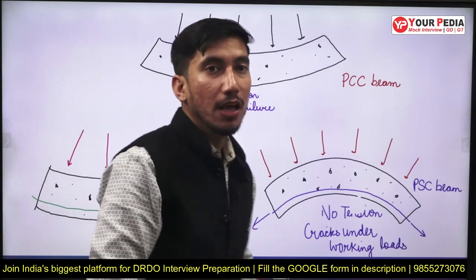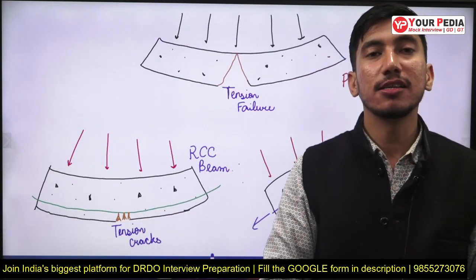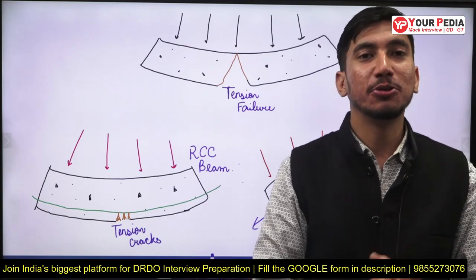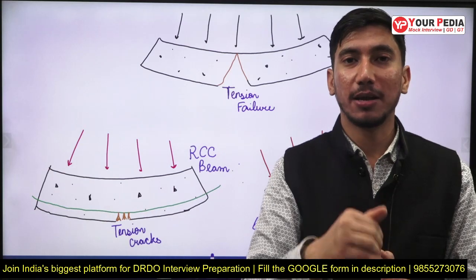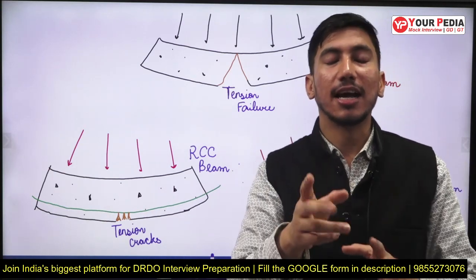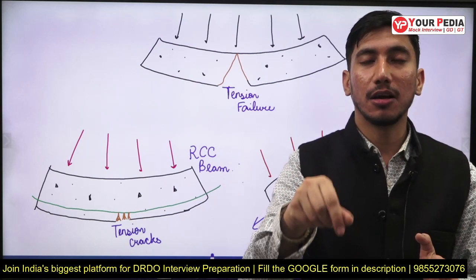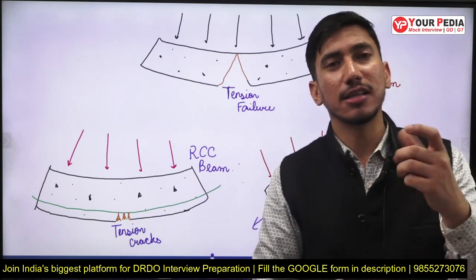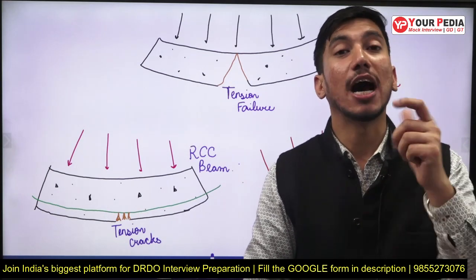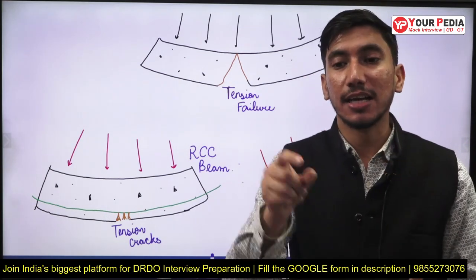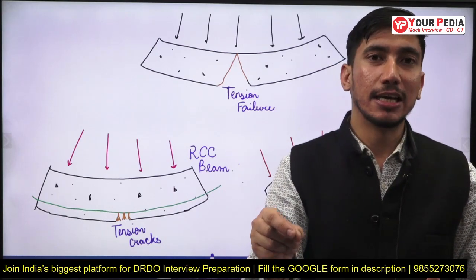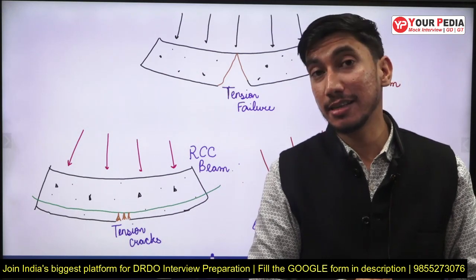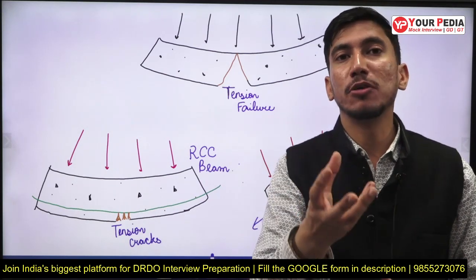Okay. So now this I have discussed. Now coming back to the question that I asked in the middle of the video, and I told you that I will tell you the answer at the last. The thing is, why do these road pavements still have steel rebars in them, and still are called CC pavements, not RCC pavements? It is because the area of the steel provided in these pavements is less than the minimum area of reinforcement prescribed in the IS code for RCC members.